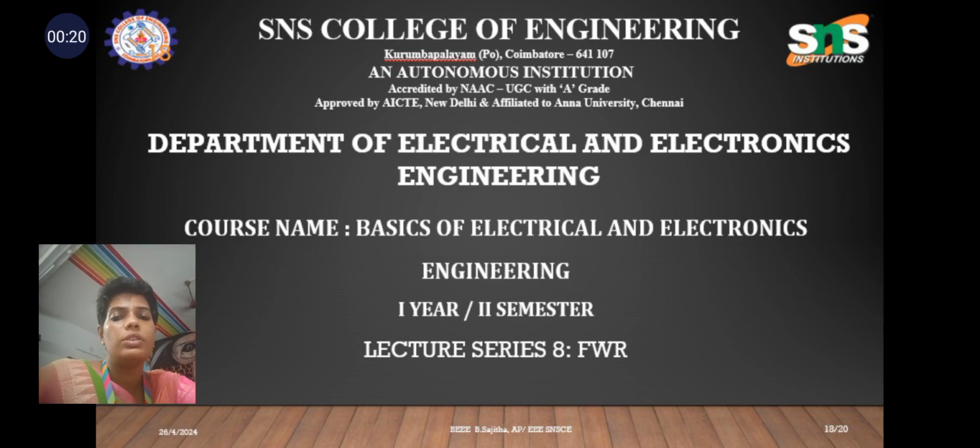This video series is again a continuation of the full wave rectifier. In the previous video we saw the different types of full wave rectifiers. One was the center tap rectifier and the other was the bridge rectifier. The primary difference was that in the center tap rectifier there were only two diodes in the circuit, whereas in the bridge rectifier there were four diodes connected in the circuit.